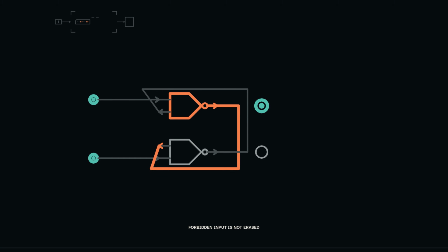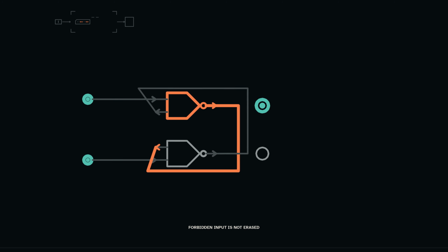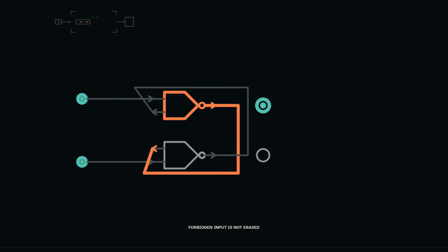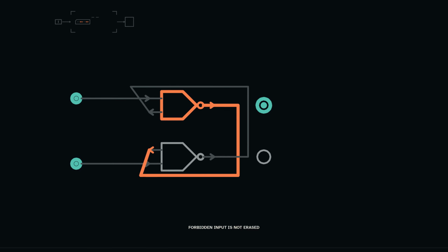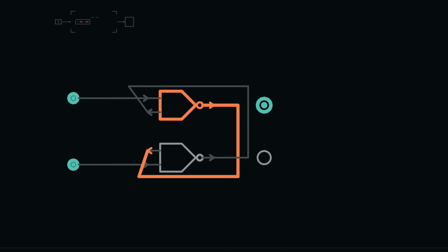1, 1, 0, 0. The two hold rows cannot be answered from current controls alone because both rows have the same external pair. Their different answers come from the different states entering those rows. That is a direct test of sequential rather than combinational behavior.